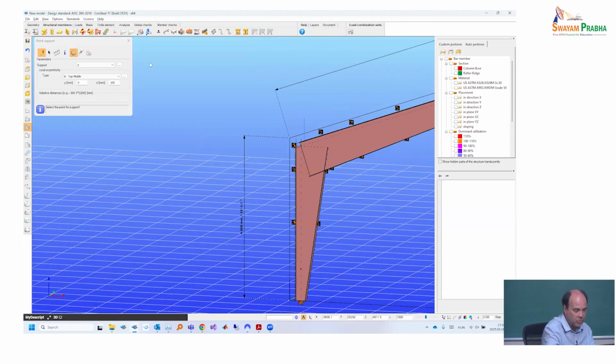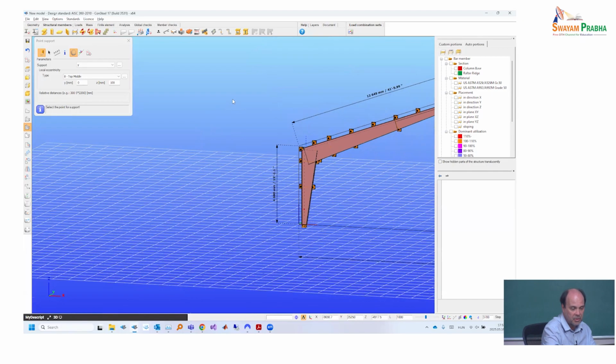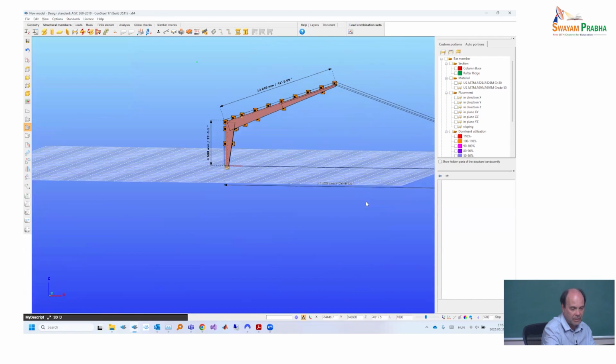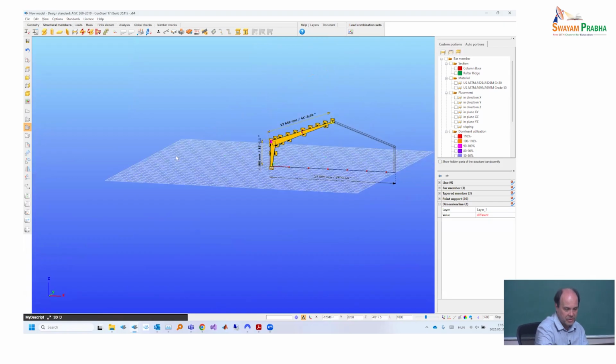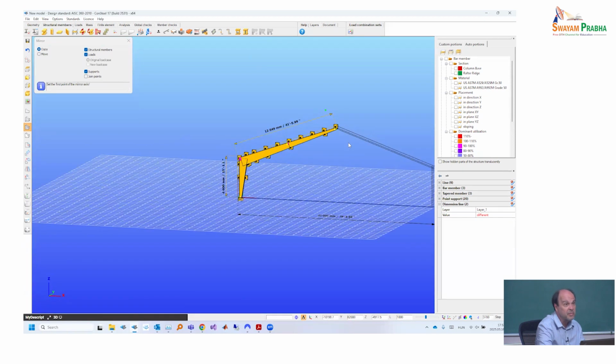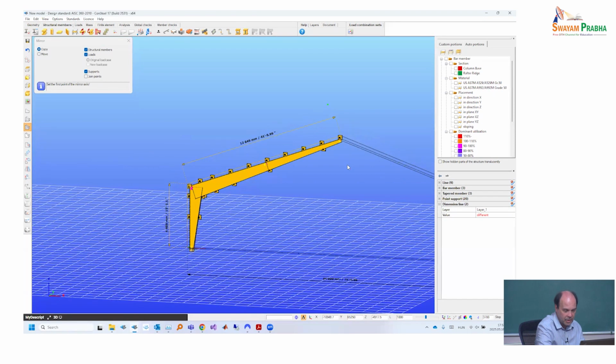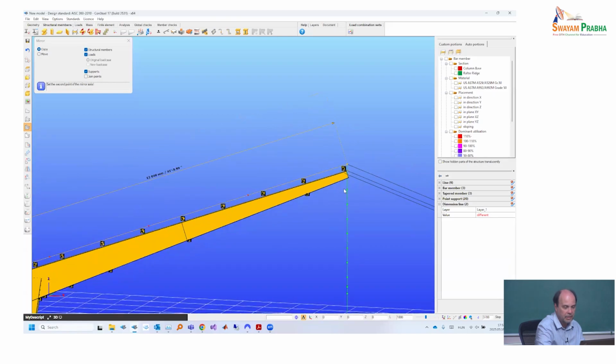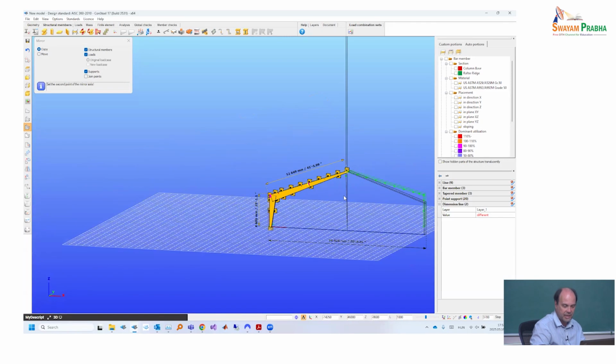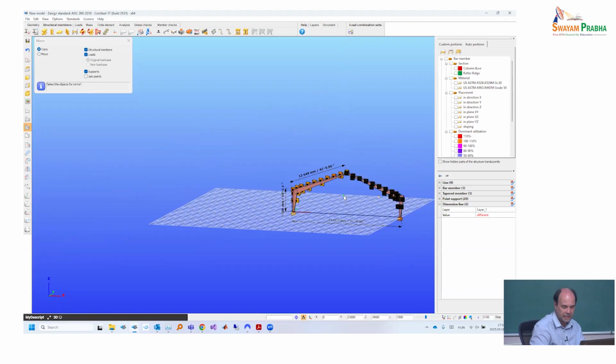Now we are at the moment to mirror everything. I can also just simply select everything. That's the simplest. Doesn't matter if there will be some extra lines. Doesn't matter. So I select everything. Come to the mirror function. And we will be ready exactly at 6 o'clock. I click on the line, press X, 0, enter, and we are ready for today.